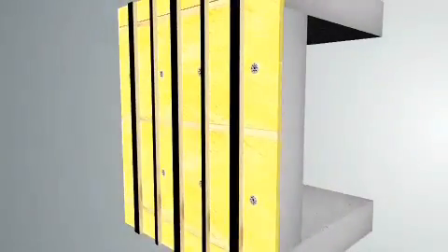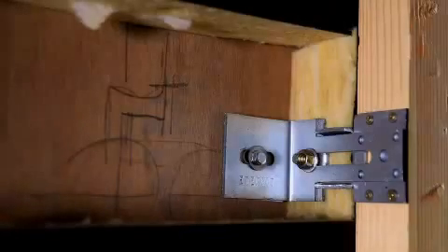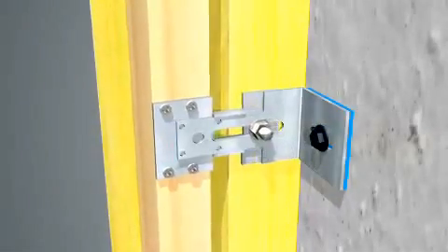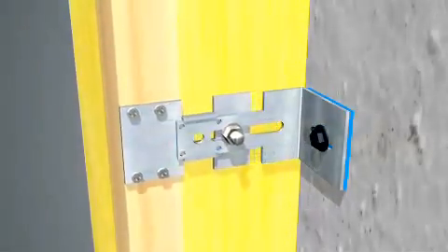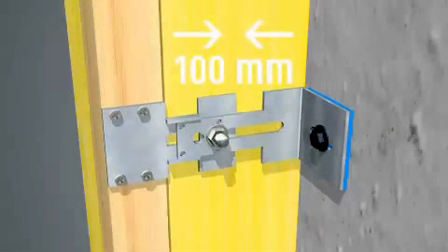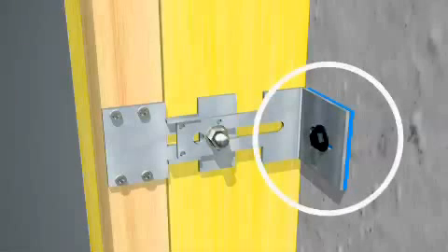To accommodate the insulation and maintain the cavity, the vertical battens are fixed back to the structure in a number of ways. Adjustable system. This system utilises the Eternit adjustable bracket to carry the vertical batten. This allows for batten adjustment for uneven wall surfaces and can accommodate insulation up to 100mm thick. The bracket with its thermostop is fixed to the wall with suitable bolts or screws. The brackets alternate to the left and right of the batten to ensure stability.